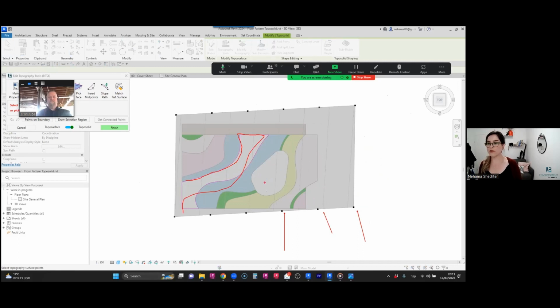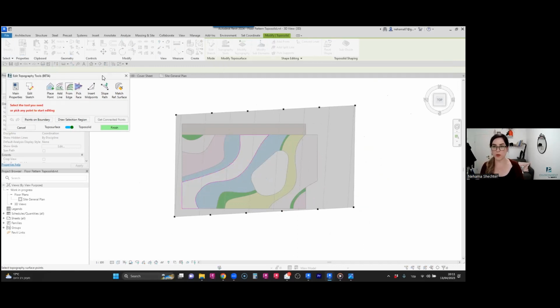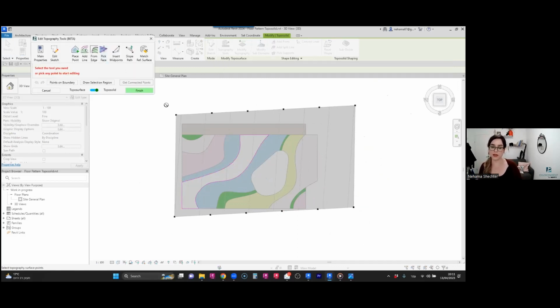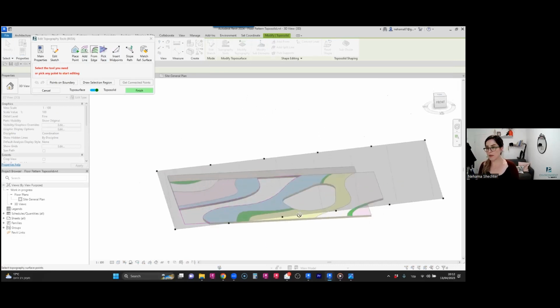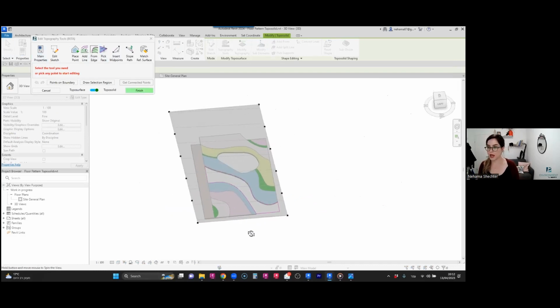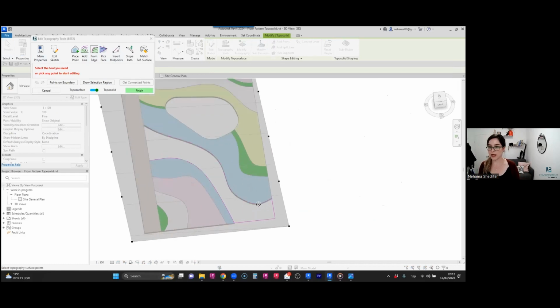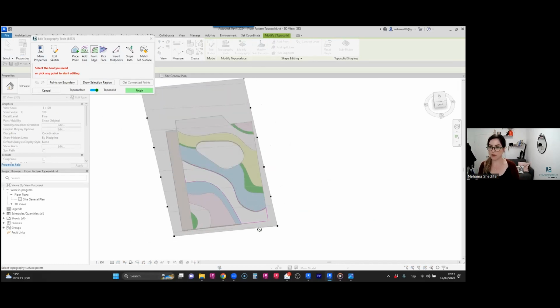That's a really convenient way to work. We call this concept the reference surface. It's basically an invisible surface that exists only within the Environment topography editing tools. And you can see that it allowed me to edit a very complicated shape with such a small amount of elevation points.